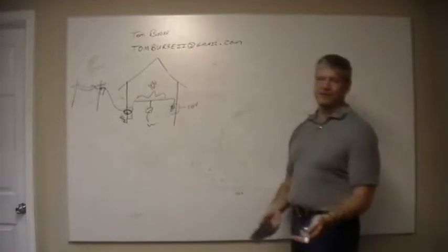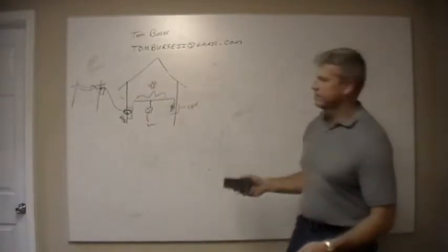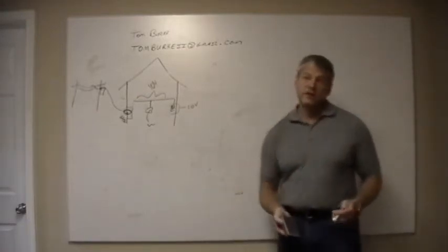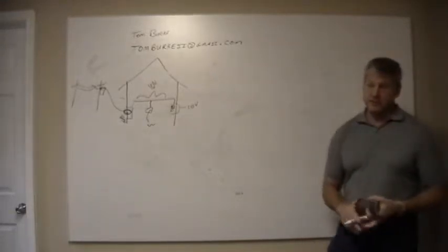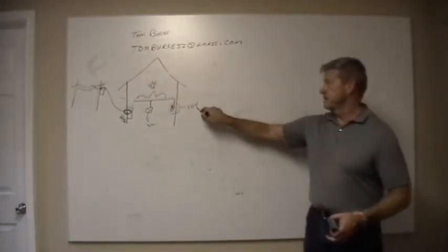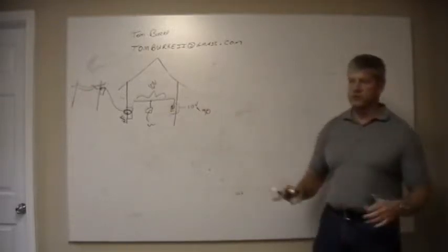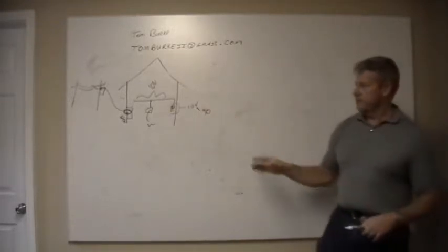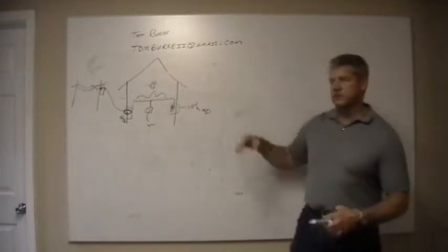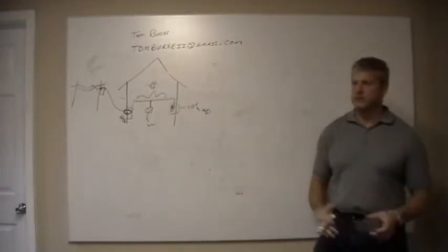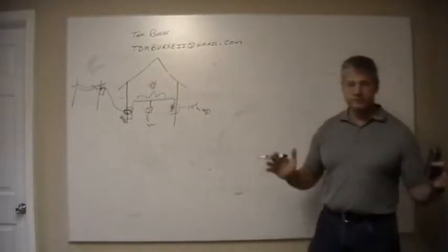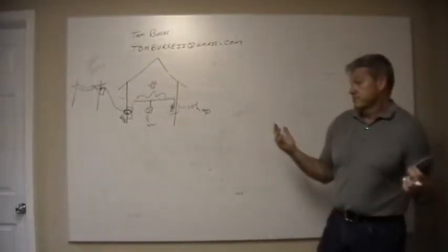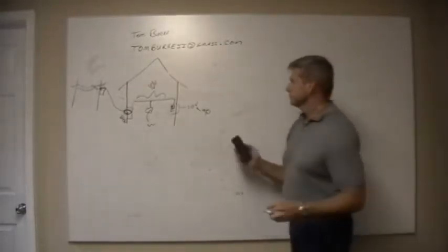It's sloppy, and when you design a circuit, you have to take into account the two extremes, right? And in a brownout situation, this can drop down to 90 in the worst case. And then power spikes can bring it up. You usually talk about plus or minus 10%. So you want to be, you know, between 130 and 100 that your system will work, because stuff happens sometimes.